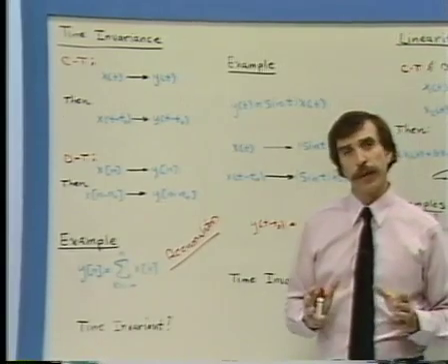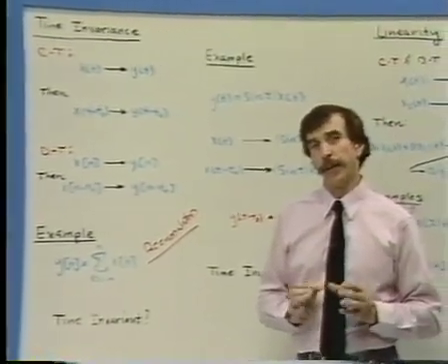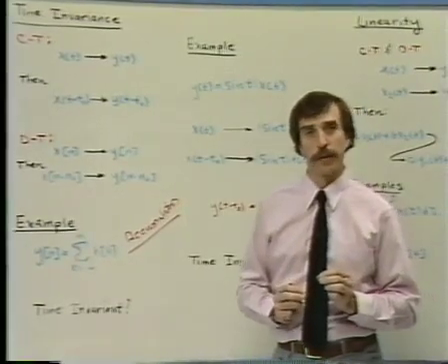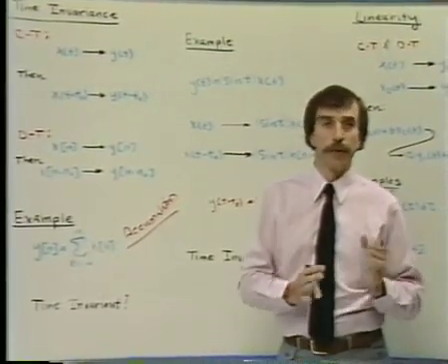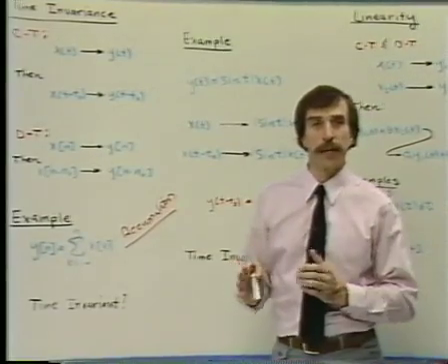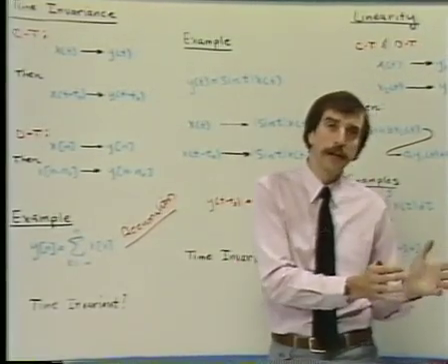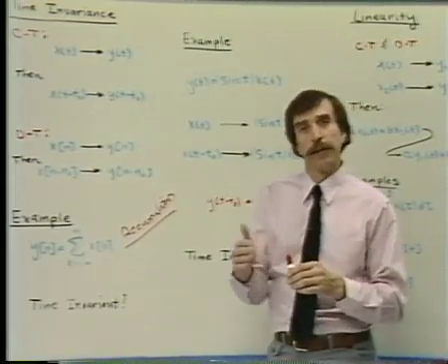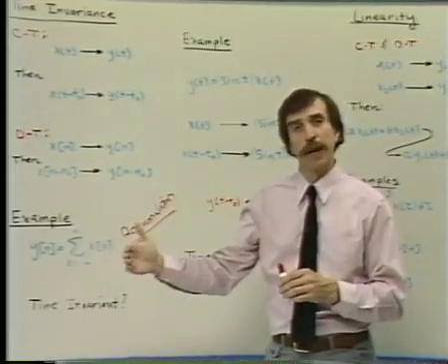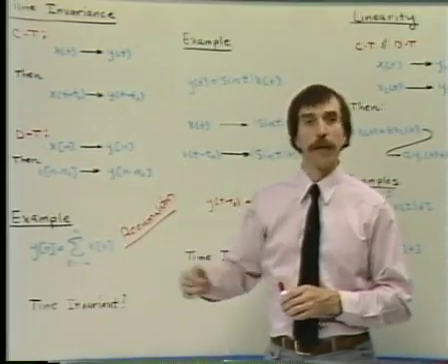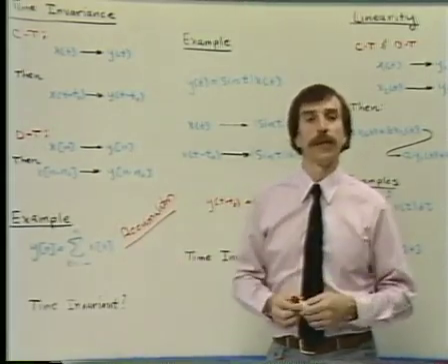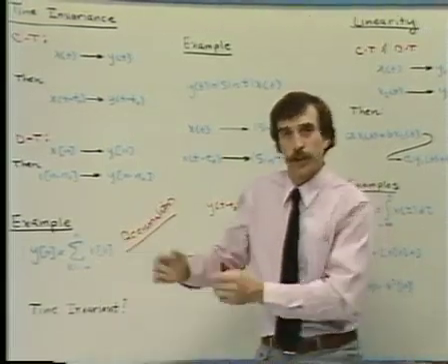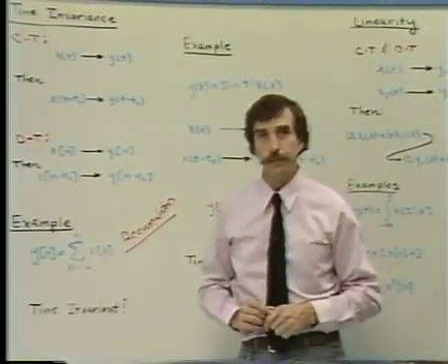Informally, it makes intuitive sense that the accumulator is time invariant, because if you delay the values that you're putting into the accumulator, then the associated values that come out will be delayed by the same amount. The accumulator doesn't care if you shift the input, it'll just simply shift the associated output.